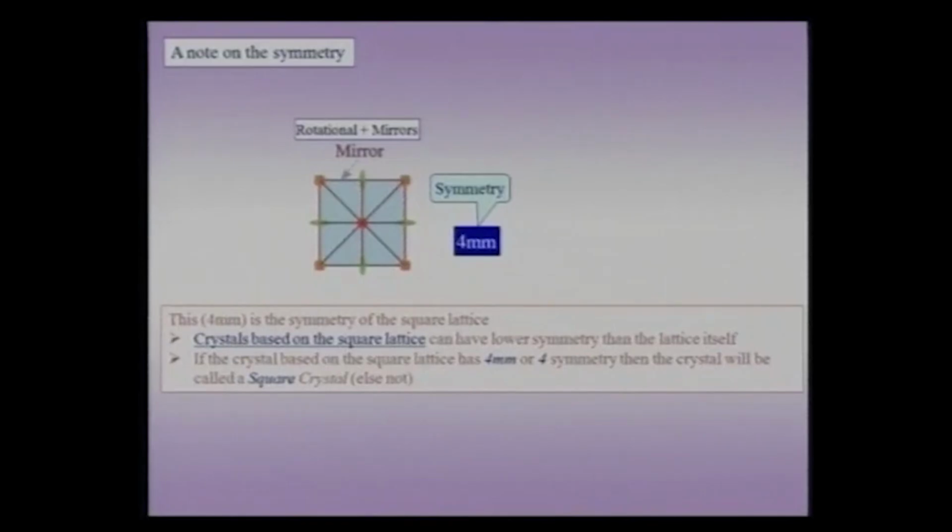So at this point, all I need you to understand is that there are more considerations than just the symmetry of the lattice or the shape of the unit cell of the lattice which go into defining crystals. If I place a motif of a lower symmetry than the symmetry of the lattice, then that motif can alter the symmetry of the crystal I have generated, and the original symmetry of the lattice may be lowered or may even be completely destroyed.